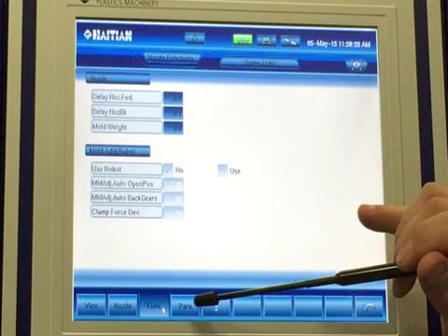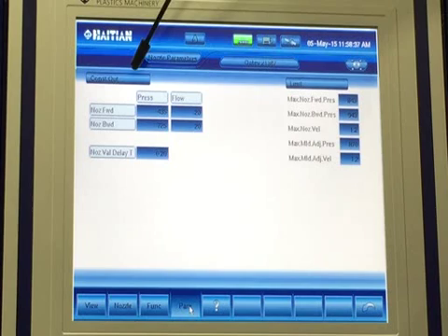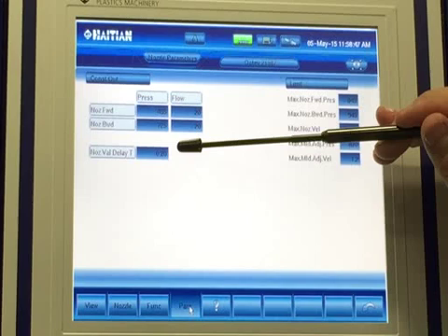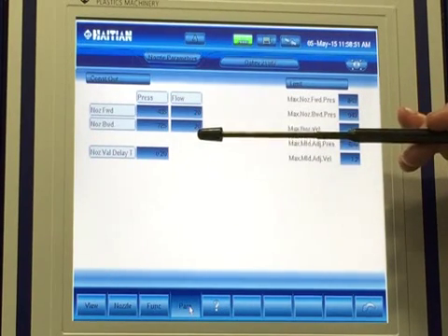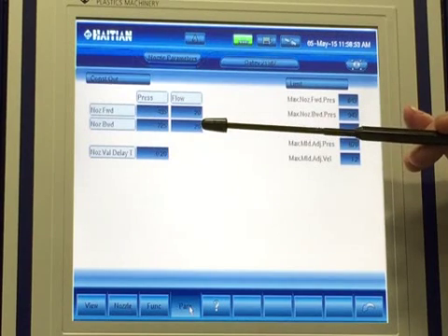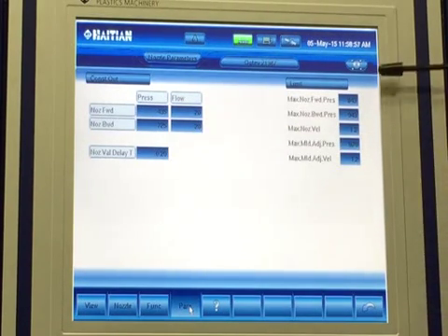The next screen is the parameter screen. We have constant output for pressure and flow, where these are the pressure and flows that the machine is going to use to move the carriage in the setup mode. Nozzle valve delay time. This is if you have a shut-off nozzle on the machine. This is just the delay time for that function to happen. Then you have pressure and flow limits on the right-hand side of the screen.